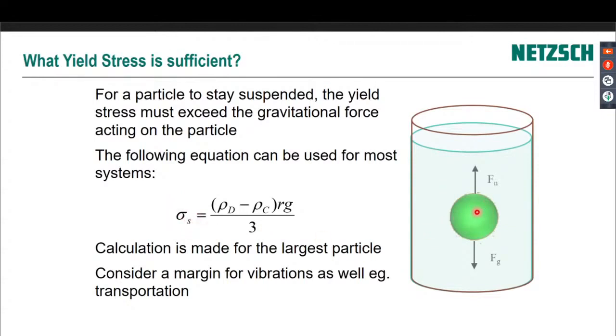It should just stay put. So it'd be like peas, for instance, trying to sediment through hair gel. They shouldn't be able to move because the gel's just too stiff. But if you put peas in a low viscosity liquid, a thinner soup, for instance, then the peas will sediment to the bottom. So this is a pretty quick calculation to do. You just need to know the particle size and the density of the pea and the density of the continuous phase, and you can do that calculation.